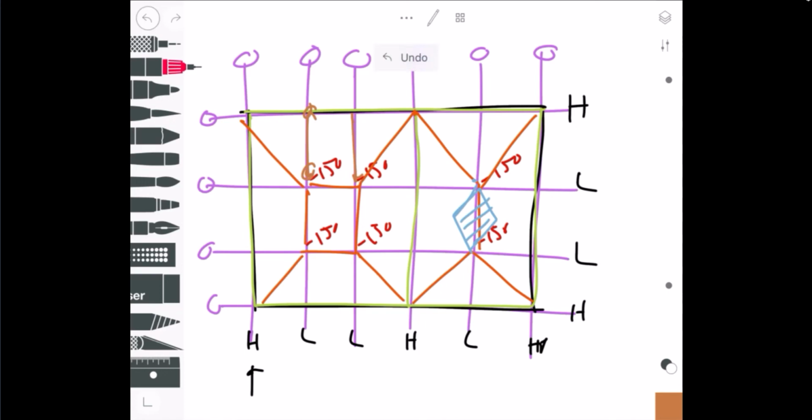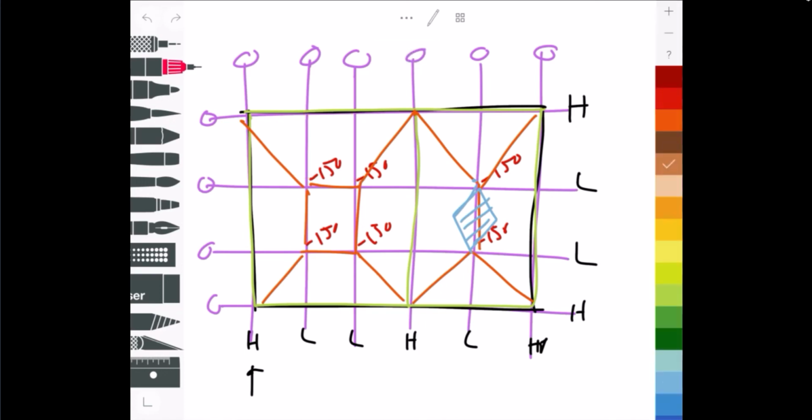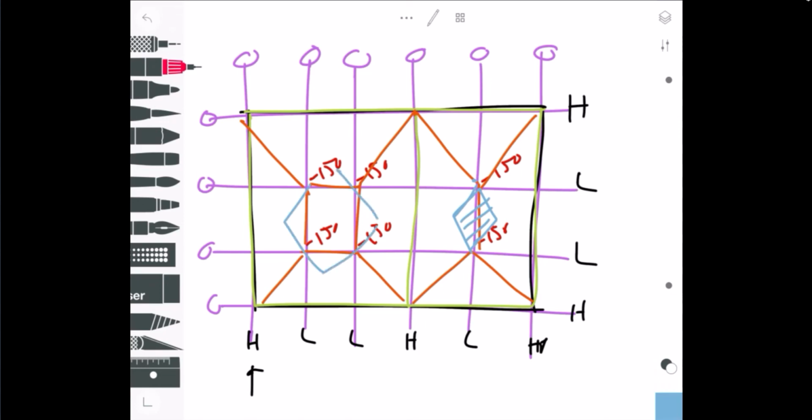But it happens, and in this case, it would still be beneficial to slope your structure and then just approach that flat spot the same way. I guess it would look something like that. It'd be like a diamond type thing. There'd be a high point in the middle of this thing and tapered insulation outwards, so that when water comes down, it gets down to a drain. So you'd put a drain around each one of these points, I guess, something like that.